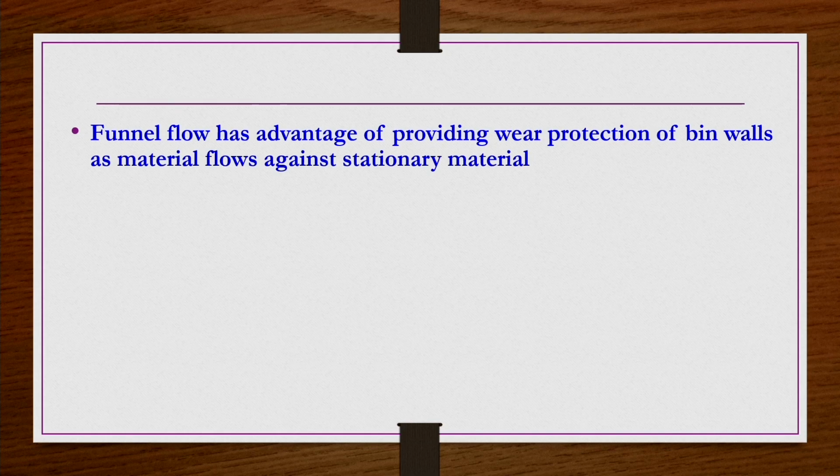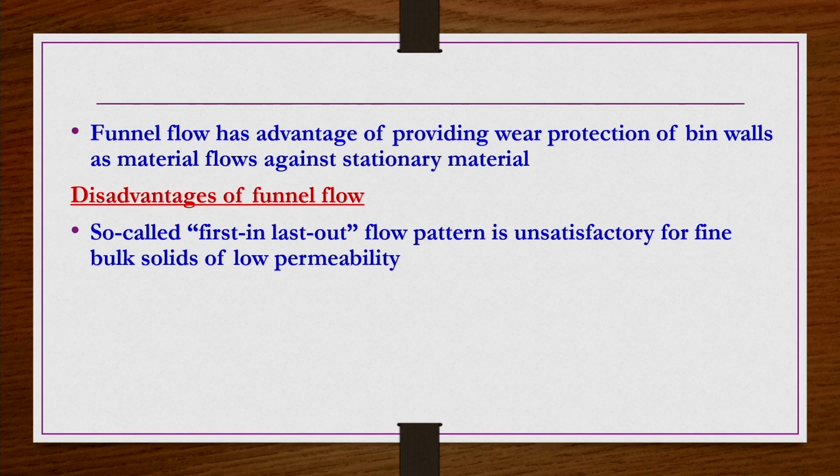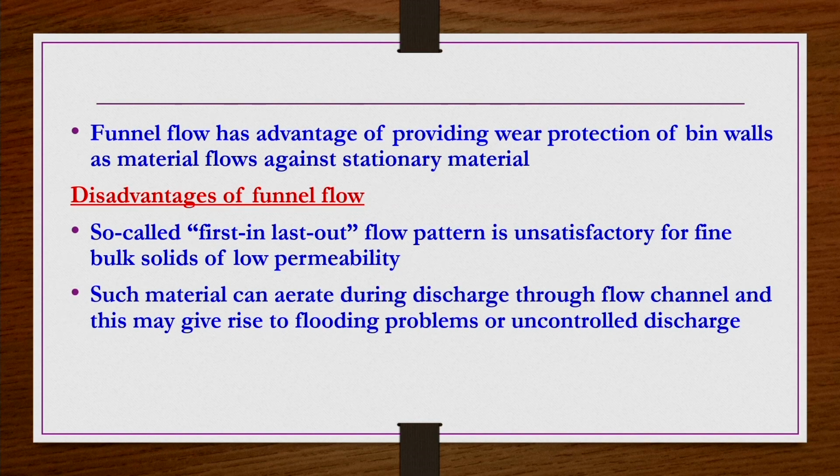Though that is the only advantage of funnel flow, there are several disadvantages. One is the so-called first-in last-out flow pattern, where the material which enters first leaves last, only after all the top material has flowed out. This is unsatisfactory, especially for fine bulk solids of low permeability. Such materials can aerate during discharge through the flow channel, and this may give rise to flooding problems or uncontrolled discharge. That is another problem associated with funnel flow bins.